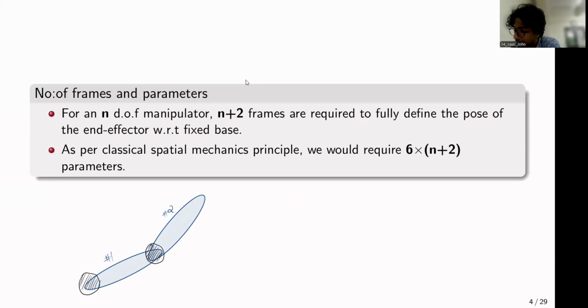So if you consider the tip of link 2 as the end effector, because at the tip of link 2 you would be attaching a tool, maybe like a gripper, obviously you need two frames attached to two of these rigid bodies, something like this. I'll call this Z1, X1, Y1, and one more frame for link 2, that will be Z2, X2, and Y2.